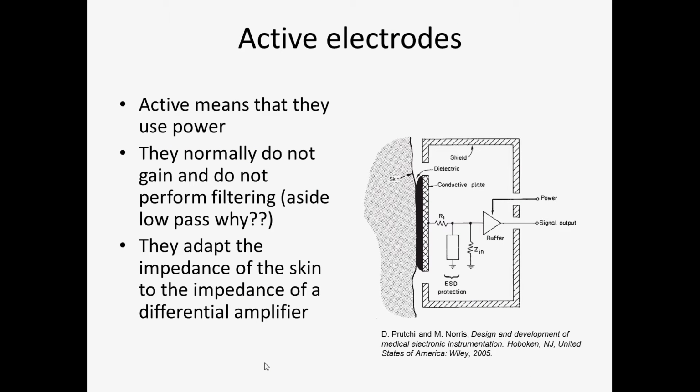One other thing that you might encounter: the active electrodes. Active electrodes actually merge together amplifiers and electrodes to reduce the noise capture of wires. If you have done EEG recording, you know what is going to happen if the participant moves the head completely. And probably that's the reason why the wires connected to the head come from above the ceiling, to avoid big movement. Because if you swing the wire, you're going to swing the traces.